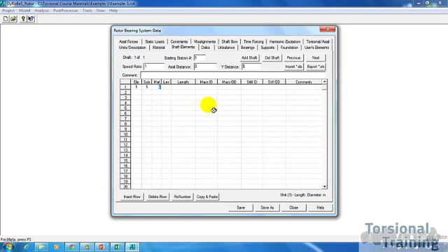as well. Now what the sub is, it's sort of a, for very long rotors, for very big models, it's very useful to use sub elements because it helps with reducing the computation time. In our particular case, since we're building one element, it doesn't matter, so you just keep one sub element. Now under material, type material 1, and I'll explain why you type material 1 in a second. Under level, type 0.